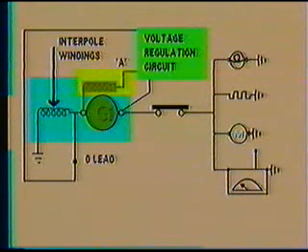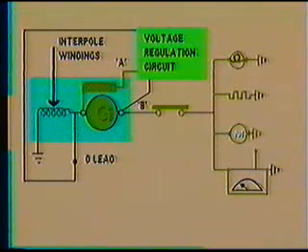Returning to our pump analogy, we can think of the A-lead as a governor connection, a smaller force that is able to regulate the output of a larger force. The B terminal is the output junction of the generator. The power being delivered by the generator for use on board the aircraft is delivered here. The B lead terminal is also a connection point for the control panel for sensing and monitoring the voltage output of the generator circuit.